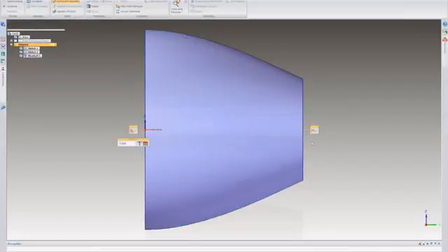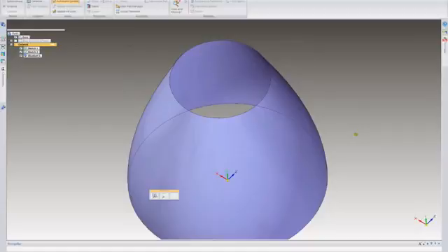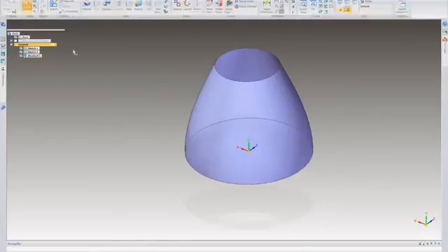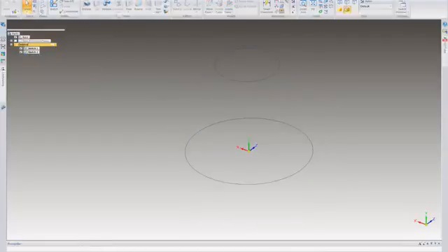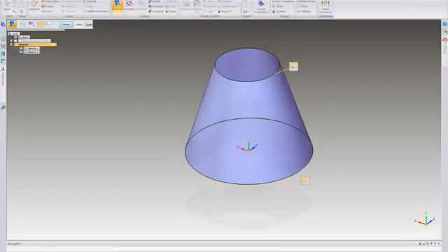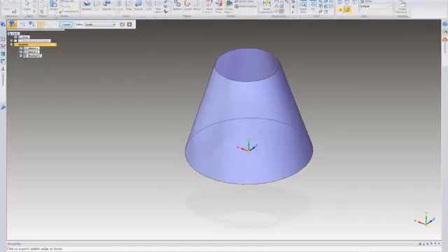All right. So what I was going to do is create some text. And of course, the ability to create text on a geometry, if you want to wrap it or project it. If you want to wrap it, you would want to use... Oops. Sorry, I didn't mean to undo that. To make a wrap sketch, the criteria is that the surface has to be tangent to the actual plane that you're working with. So I'm going to create a sketch on that surface.